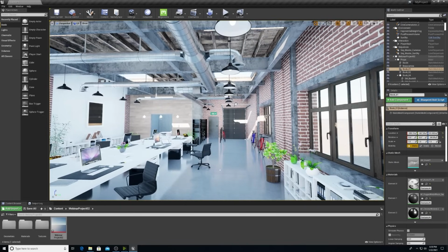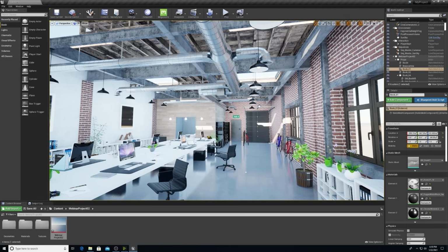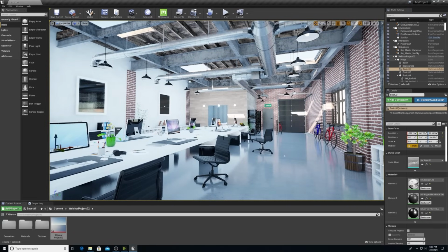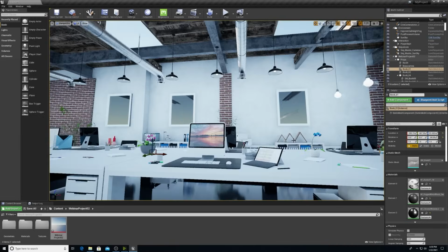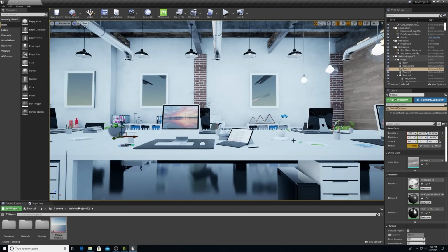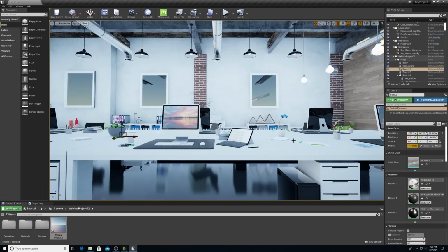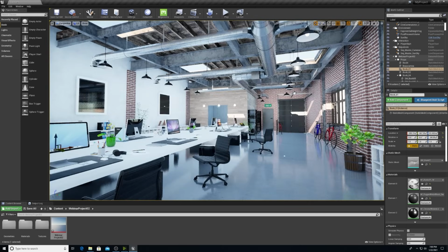So now that I have everything in, ray tracing turned on, I'm going to set up some views. They're called bookmarks, and what I'll be doing is getting to a view that I like. I'll hold down Control 1, and now I'll go to a different spot of the project. Hit Control 2. And now, when I press 1 and 2, it will toggle between these two views. So the Control button allows you to initially set those, but you can also do that by going to the top left-hand corner, selecting the drop-down button, going to bookmarks, set bookmark, and then you'll be able to jump between the two that you set up.